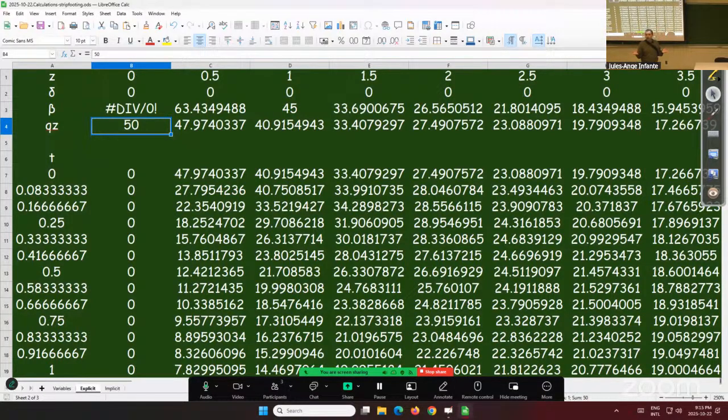Actually, they had that problem in Boston, the Big Dig, where they had used undrained shear strength parameters for the clay. And they designed their shoring based on that. But all the seams, like you need to be certain that your clay will keep its strength long enough, right? So you can do a pore pressure distribution, but you need to make sure you have a proper view of the whole profile.